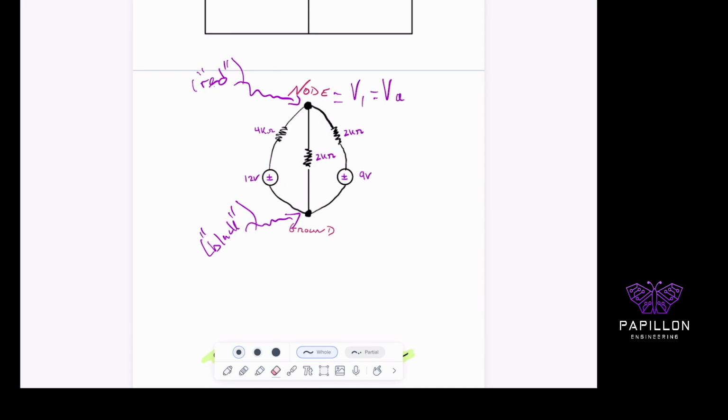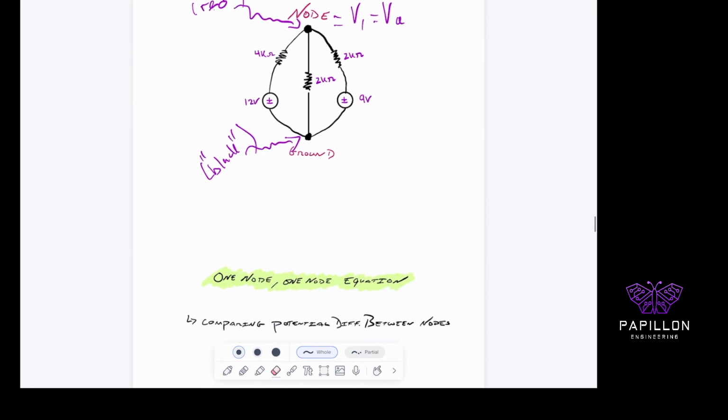It's saying that from a practical standpoint, if I get my voltmeter out and I connect my red lead to the top of the node, and my ground, or my black clamp, to the bottom of that node, I should get the same voltage across all of those 3 parallel pieces. So node voltage is the net voltage of a branch. That's super, super important.